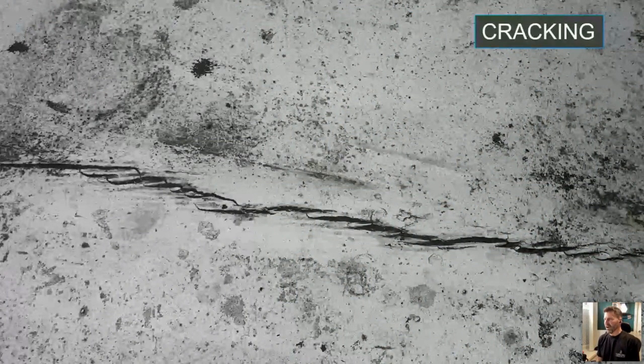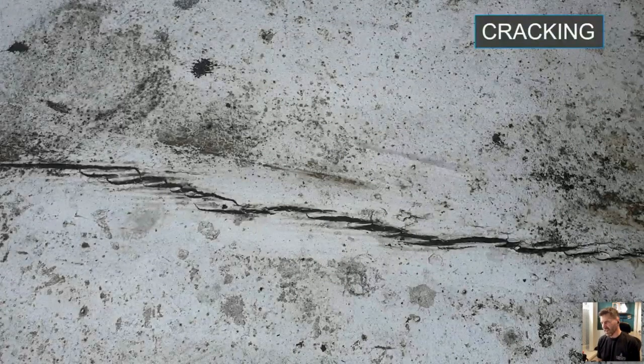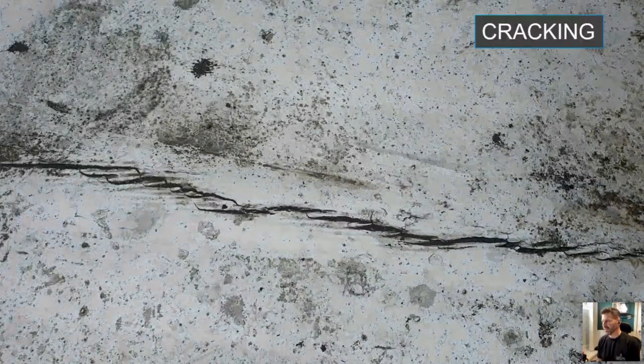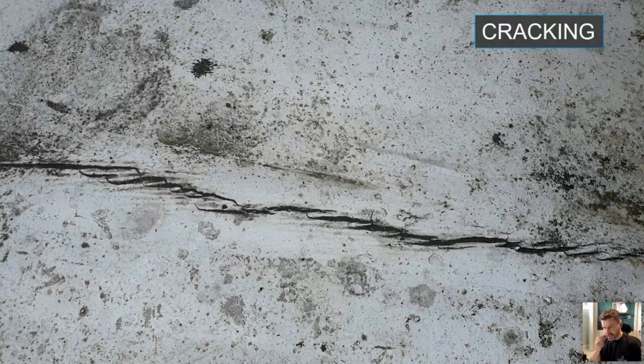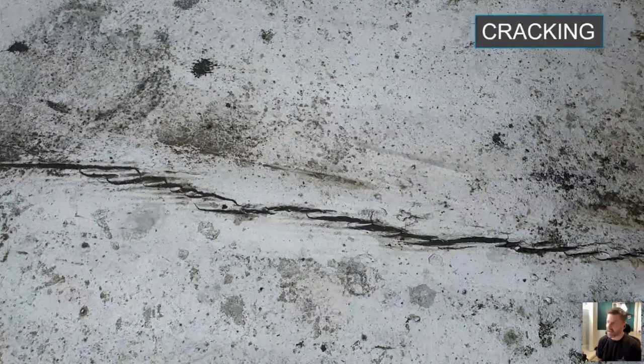This happens over time, or certainly in older oxidized asphalt systems before SBS and other modifications were introduced to make it more elastomeric and more stretchy. But over time, obviously, asphalt can lose these properties, and over movement joints with expansion and contraction, it can start to crack due to age.